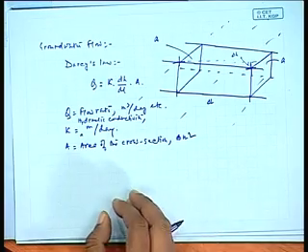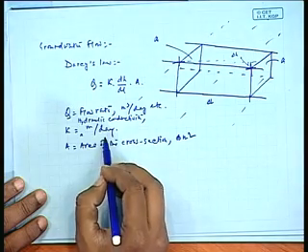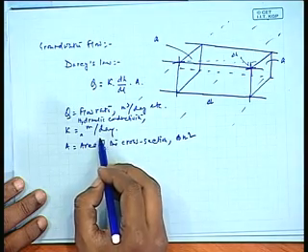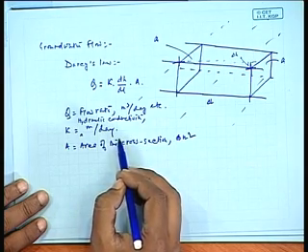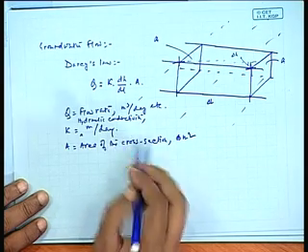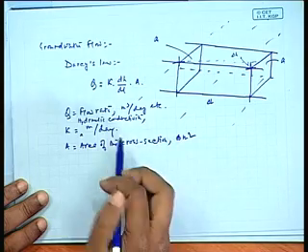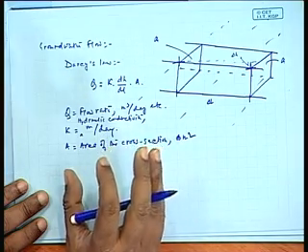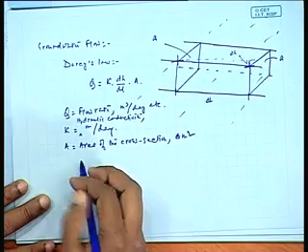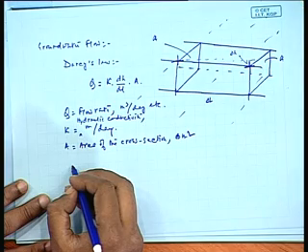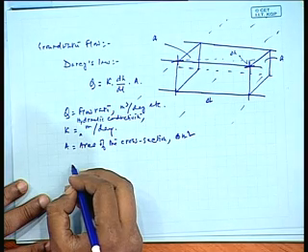That is how the time rate coefficient is represented, because in many cases the speed is very slow in an aquifer, so we generally need not represent it in terms of minutes or seconds. Mostly representing it in terms of day is fair enough, because the velocity is very low. So you can see this is known as Darcy's law.